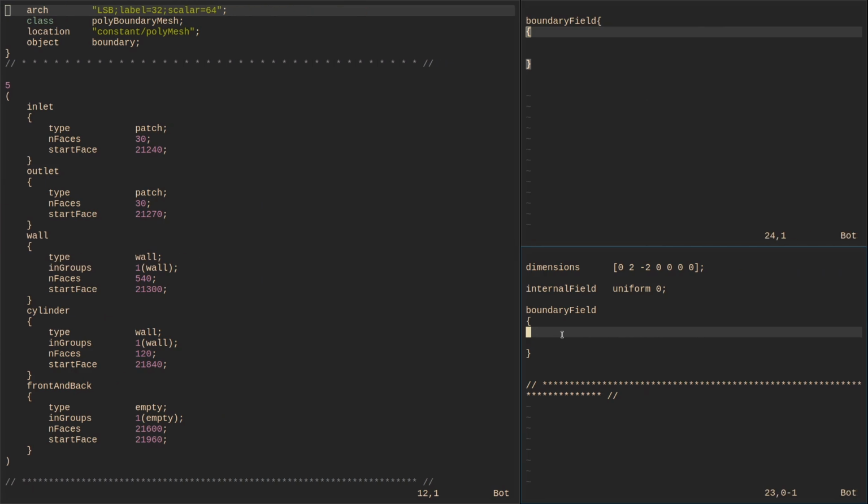Before we write, let me share a habit that will save you a lot of time. Whenever you are about to use a boundary condition for the first time, go and open its header file. The header file tells you exactly what the condition does and how to use it in the field file in plain, direct language. This is the fastest way to get help, I guess.